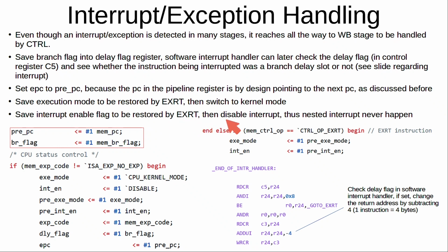And while handling the interrupt or exception, the hardware automatically disables the interrupt, and therefore we simplify the design such that we don't have to consider nested interrupt.